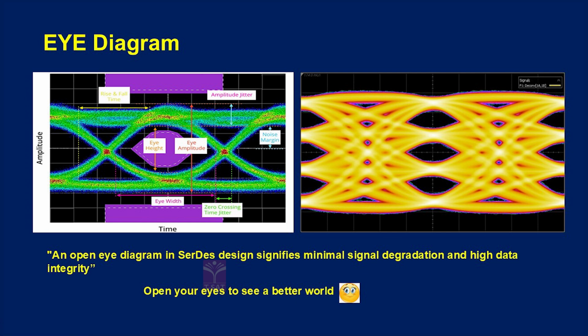Eye diagram is another way. For signal integrity, we would like to see the health of this eye. You can look at multiple such eye diagrams, but the eye diagram tells us about the health of the media. When data is transferred from transmitter to receiver through the media, the signal energy has to transfer properly. There should be good matching, and then the other factors will be incorporated. All those signal integrity factors I have shown.